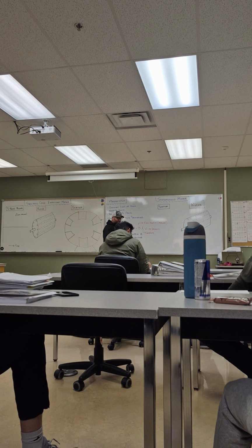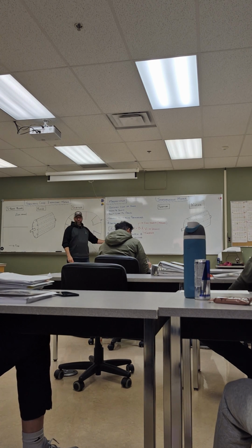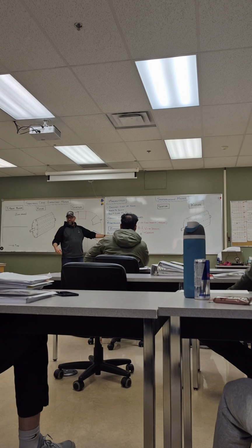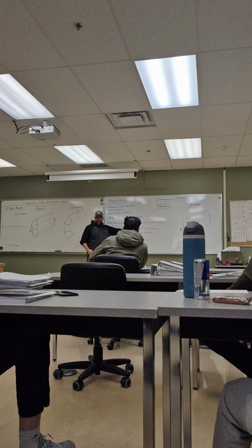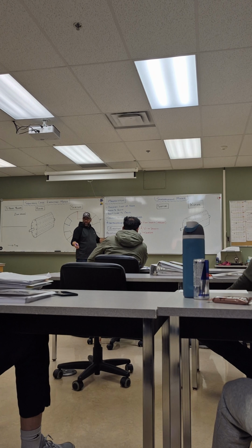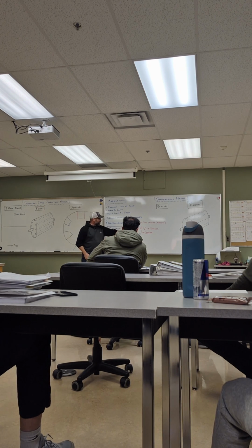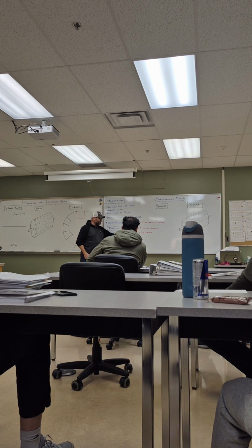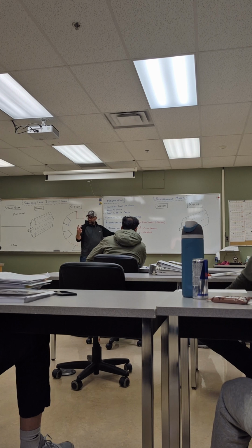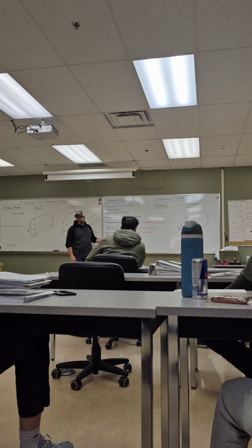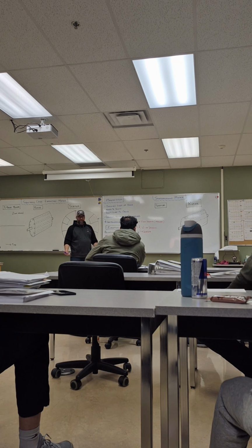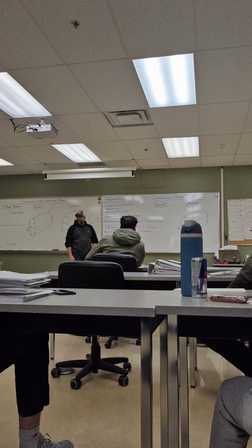Man, that's awesome. Because with this statement right here, what we just talked about, relative motion induces voltage. How much voltage? Well, as long as you have flux density, well, that's our magnetic field we're talking about, absolutely. As long as you have that, and as long as you have a length of wire, well, that's our conductor we're talking about here. So there's those two parts, and then you have a velocity. Well, that is the relative motion. And so it's like, aha, that actually explains how we get induction to take place. We induce voltage on a conductor.